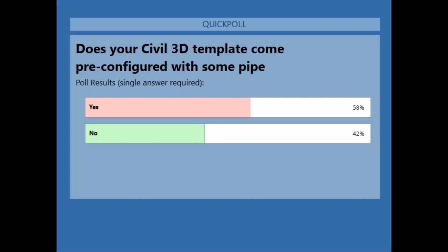Let's say you change the style of this pipe. See, there's a pay item already attached to that. Let's call it a 100 millimeter pay item. Just changing the style will not change the pay item for that. So pay items are good, QTO is good, but it is fraught with the potential for error, because sometimes you change styles of things. And like I said, if you change the style, the pay item won't necessarily get changed. So there's some potential for error with pay items.